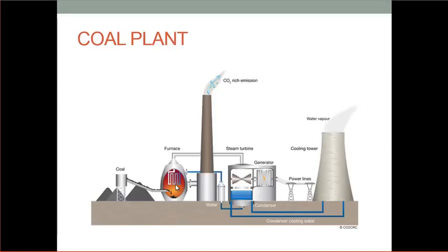So just like your car gets the best miles per gallon when you're driving it at a steady rate on the highway, and then it gets less gas mileage in traffic, stop and start, when you're going faster and slower and all that, a power plant's exactly the same thing. So if I'm base loaded and running it at the maximum efficiency, I'm getting my best heat rate out of it. And so for every pound of coal I put in there, I'm getting the maximum amount of electricity out of it.